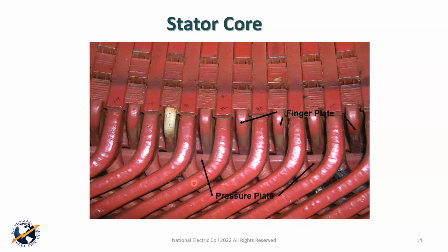If you look at wanting to get at that bottom coil, where my cursor is right there, you have to remove this one, this one, this one, this one, this one, and this one, and probably a few more to get at that one bottom coil. So you have to take out a throw, and usually 1 to 3 more than just the throw, to be able to get out one bottom coil.